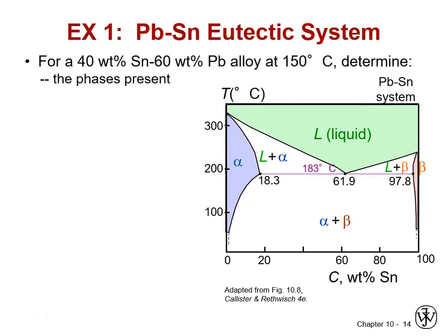So we'll go back to our unfortunately more toxic binary eutectic system, lead-tin, which was historically interesting as a solder, and that is because of its eutectic transformation. It all solidifies at a single temperature and makes it a little bit easier to do hand soldering. So in this case, our eutectic composition is 61.9 and our eutectic temperature is 183 degrees C, much cooler system.